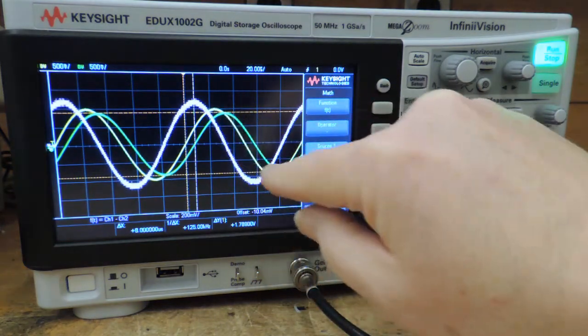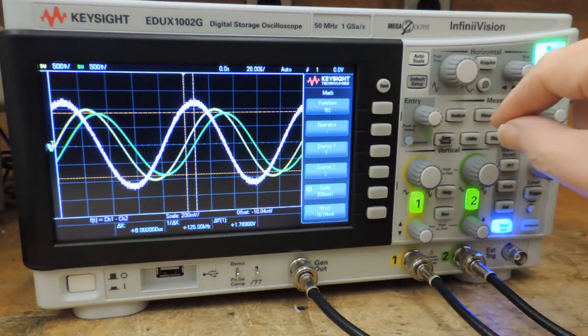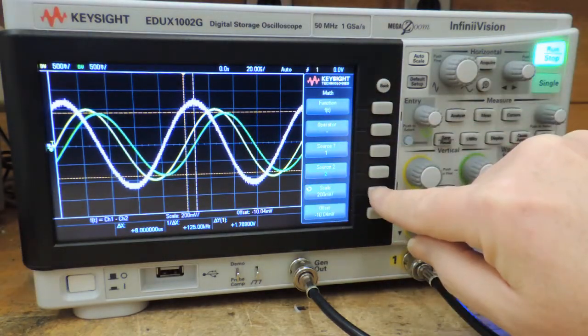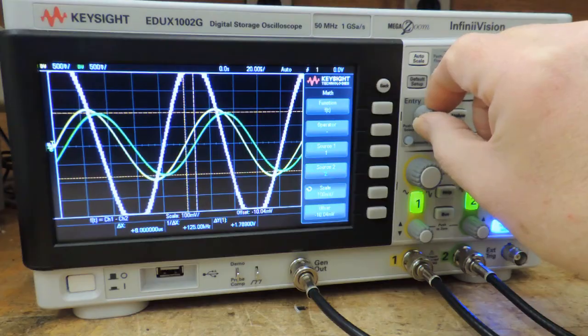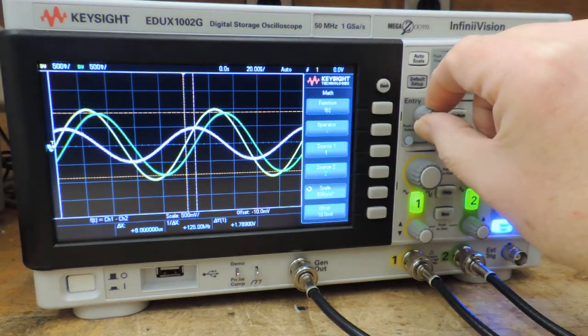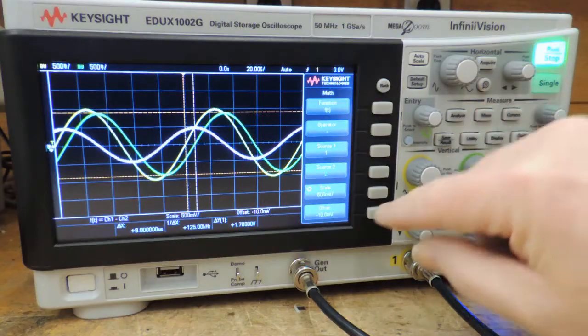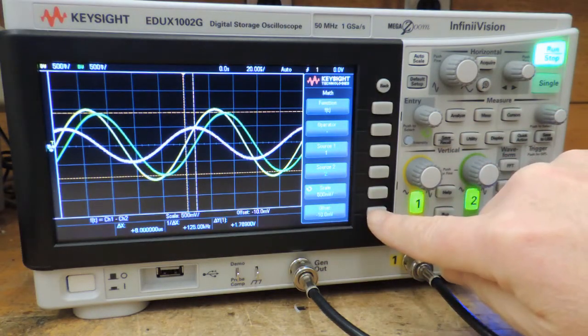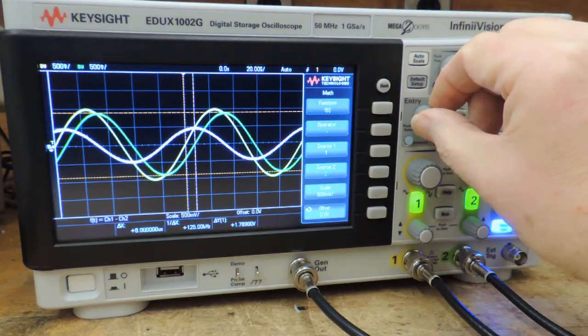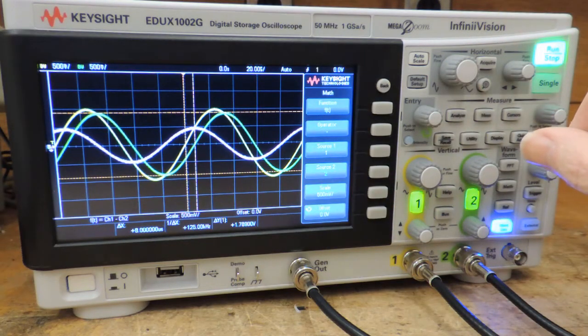So when you subtract the two waveforms, it should actually be smaller. So I'm going to change my scale so that it too is on 500 millivolts per division. Now it has an offset on here, so make sure you do click on the offset and get rid of that offset. Put it at 0 volts, or else some of your measurements are going to be wrong.